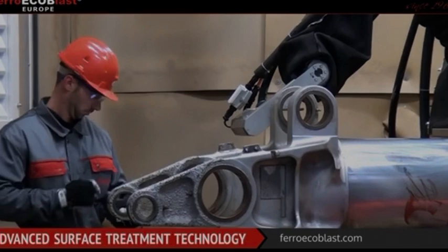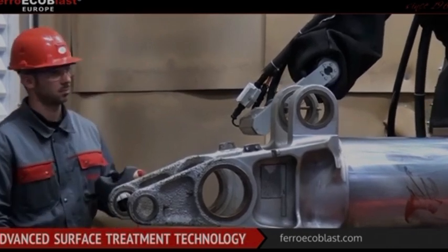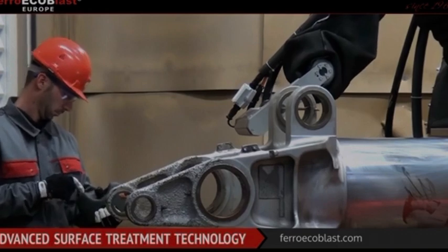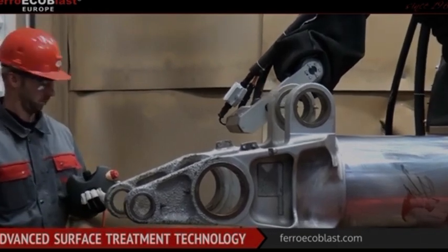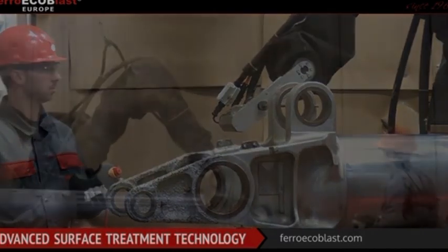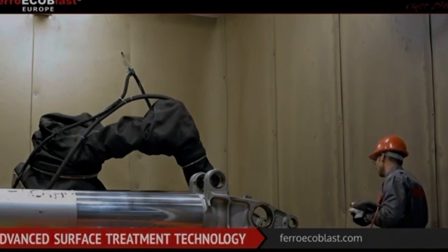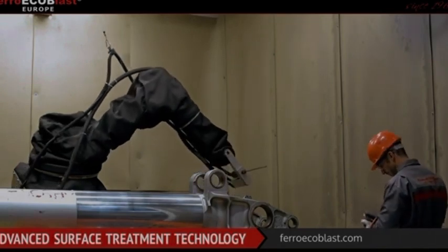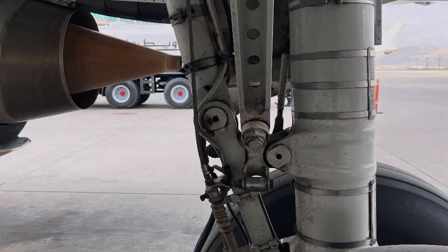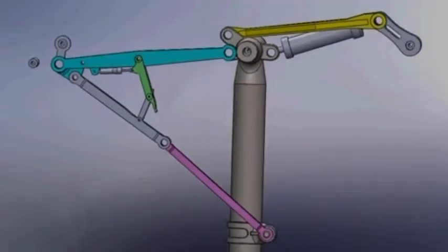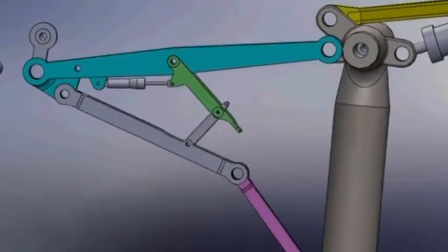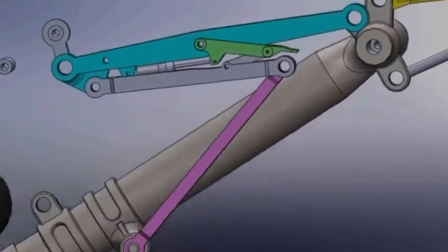For the designers and manufacturers of landing gears, when planning to design a landing gear for a new aircraft model, there are different challenges and problems to think about. The three main characteristics of every landing gear are rigidity, flexibility, and shock absorption. When the landing gears are fully down and locked, we need them to be rigid enough, so there should not be any single degree of play in the landing gear linkages. Then after takeoff, you need to break down this rigidity and change the landing gear into a flexible unit and retract it inside the housing.